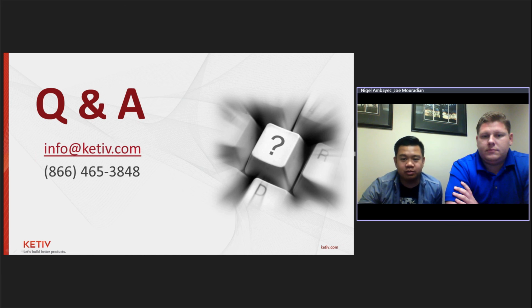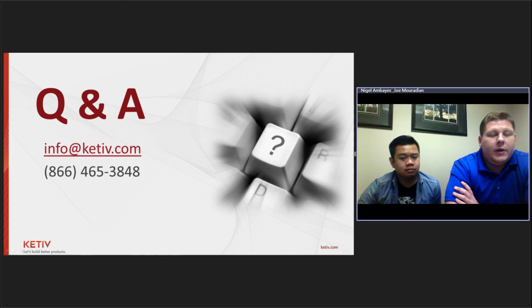So the first question here comes from Mike, and Mike asks, is Nastran In-CAD available for SolidWorks? Yes, so Nastran In-CAD is a plugin. It plugs into Inventor, and it can also plug into SolidWorks. It's either one or another. You can buy Nastran In-CAD for Inventor, or you can buy Nastran In-CAD for SolidWorks. But yes, it is a plugin. It will plug into either one of those